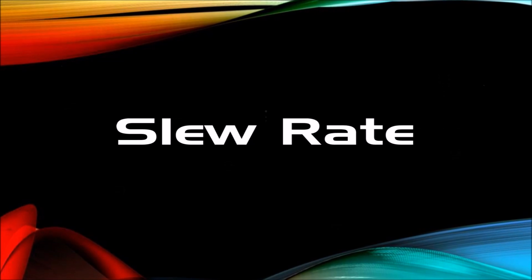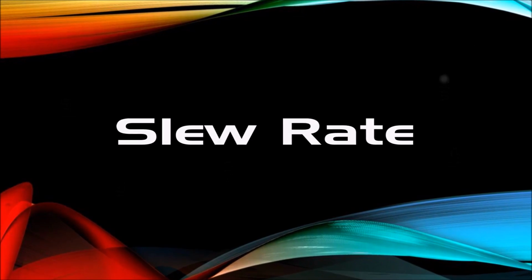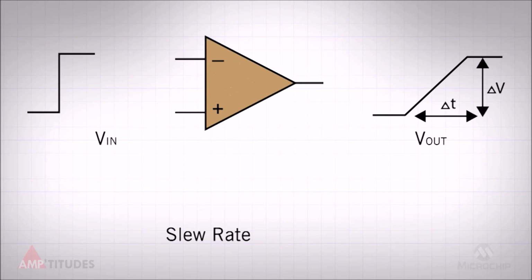Now talking about the slew rate, when it comes to the speed of the amplifier, slew rate must also be taken into account. The slew rate of an amplifier is the maximum rate of change of output voltage, and it's typically specified as volt per microsecond. In order to reproduce a signal without distortion, the amplifier must be able to change the output just as fast or faster than the input signal of interest.